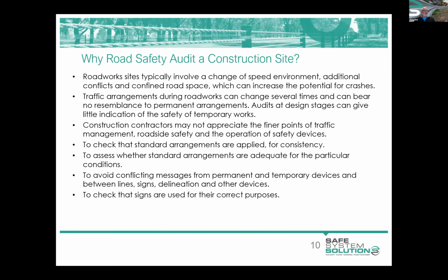To check that signs are used for their correct purpose. Yes, we often see prepare to stop used without traffic controllers being put in place. We see roadwork symbolic signs left up overnight. It's all those types of things that, under the road safety audit process, and even a compliance audit, we check, making sure that signs and devices are being used for their correct purpose and not being left up outside of our working hours.